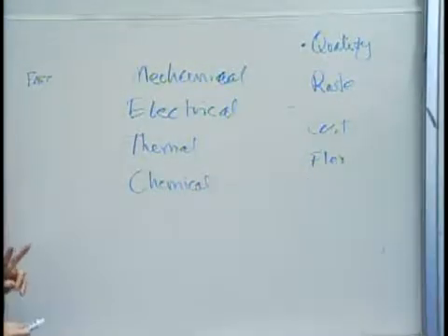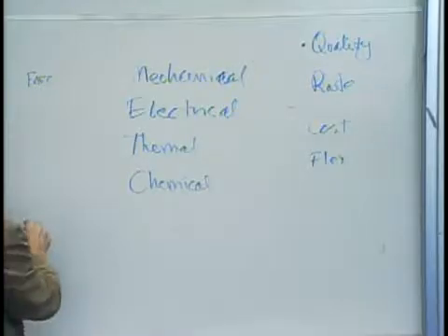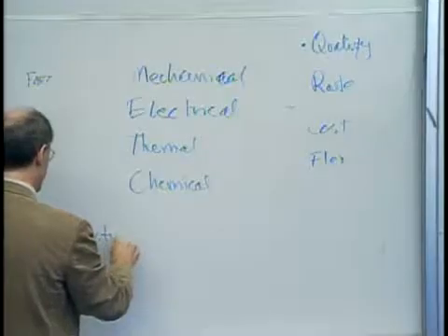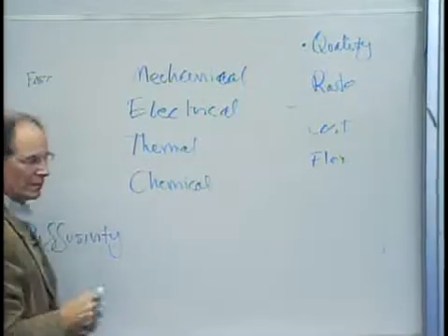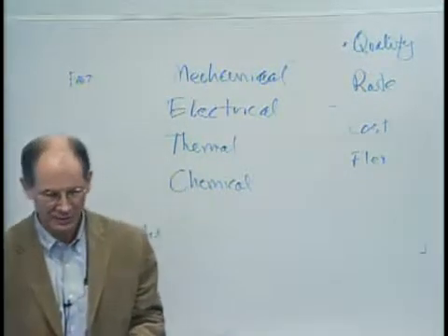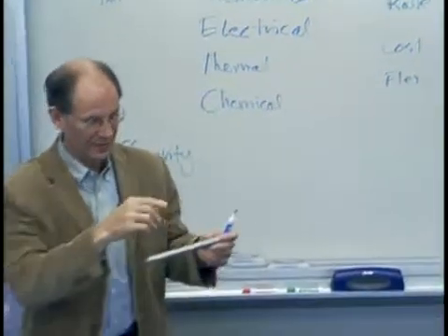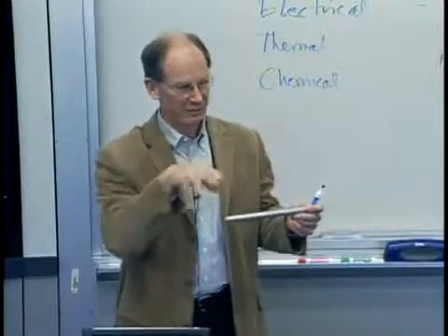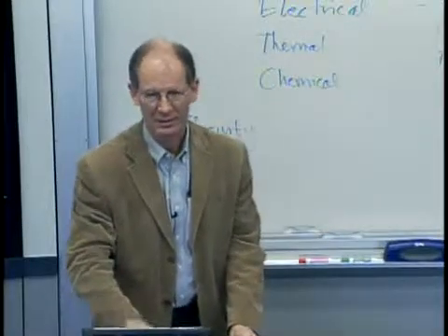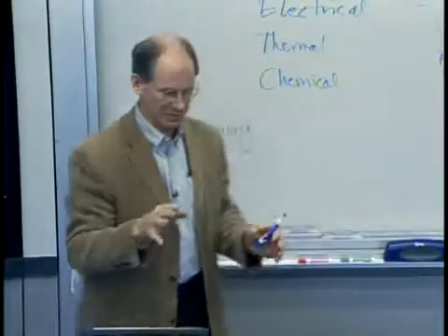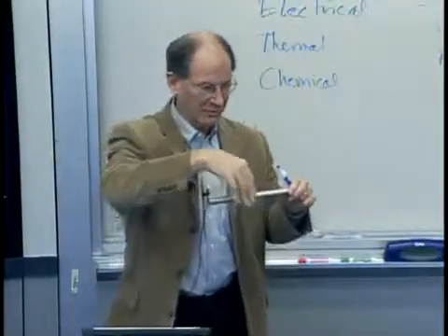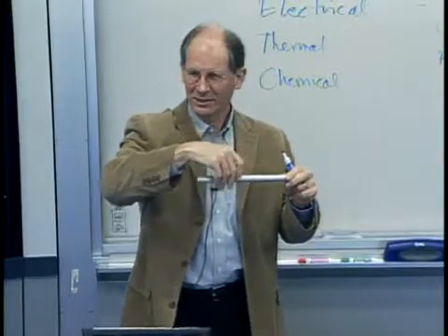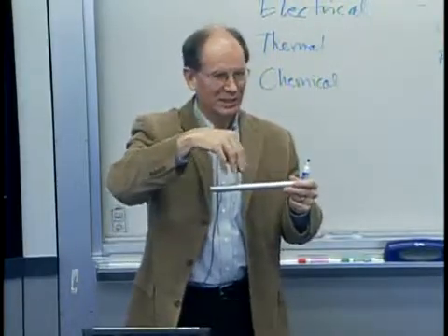So there's something here inherently related to quality. At least two things that I can think of. One of them is related to what I'll call diffusivity in the general sense, not just purely in the thermal sense. If I apply a load to something, even with a point tool, there's a stress field that develops in it and that sort of thing. And this will be a little bit facile, but I can make an argument that says, okay, if I apply that load to here, it diffuses. And so I wanted to put the load in a tiny point, but it actually spread out, and so I didn't get exactly what we want.